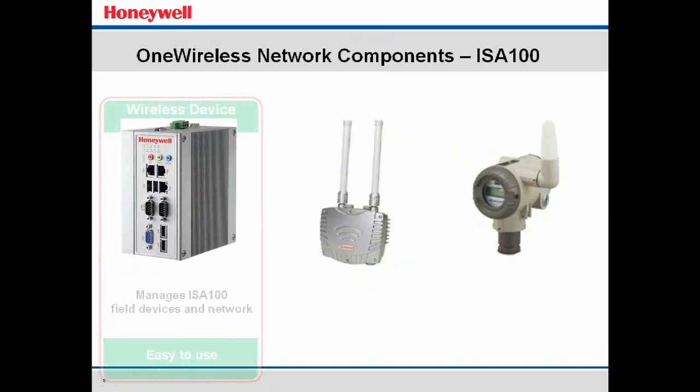You have one wireless device manager, you have one FDAP that's connected to the network, and then all of your transmitters have one single path created up through that field device access point onto the Ethernet segment back to the wireless device manager. Now the bottom one shows a more redundant setup where you have two wireless device managers because they can sit side by side in kind of a hot standby situation. If one fails, there's an automatic failover and there's no data loss. Then you have two wired FDAPs, so you've eliminated that single point of failure as well.